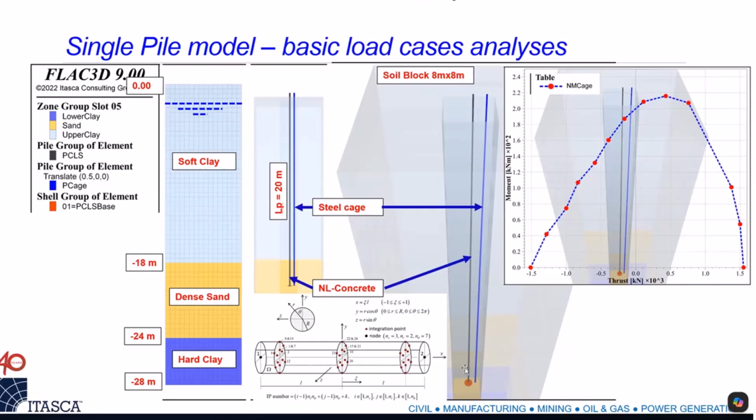of the pile. And this is important for two reasons. At the base, if you put a shell and you have a high level of mobilization because you think that the force is actually going to the base, that is rarely the case, because the pile should be designed to capture the interaction mostly with the shaft. If you really rely on the base, you are socketing in something very stiff, or it is a different type of pile, but mostly the force is going to the shaft. In any case, this can provide a better tool to capture the interaction with the base.